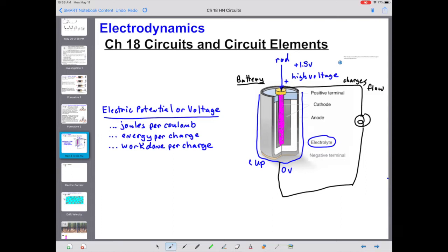So then the concept, the term of recharging a battery is very misleading. When a battery is dead, it has not run out of charge. It has completed the chemical reaction. When you recharge a battery, you do not fill it back up with charge. Rather, you apply a backwards electric potential across it to be able to reverse the chemical reaction and separate the chemicals back out. Physically, then, what you're doing is you are rebuilding or replating that central rod that had dissolved in the process of the chemical reaction.